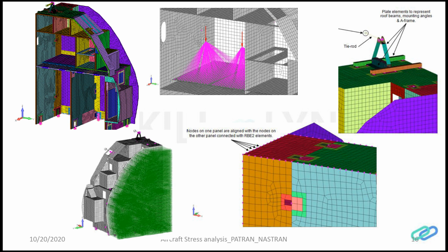It tries to move from the high pressure region to the low pressure region. That is called cabin rapid decompression. So if you look at these pressure loads, these are based on the cabin rapid decompression loads. And in terms of the mass that is being applied, I modeled the spider using RBE3, and I simply converted the mass times 9.81, which gives the force. So I applied those forces on the structure.